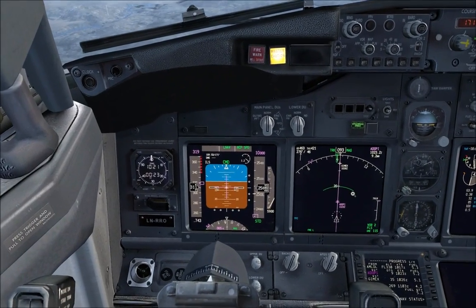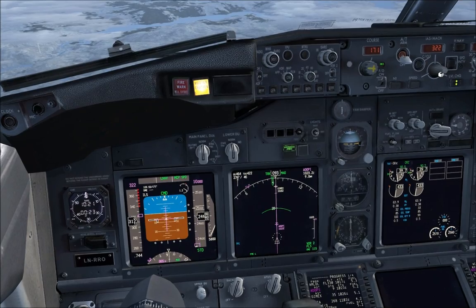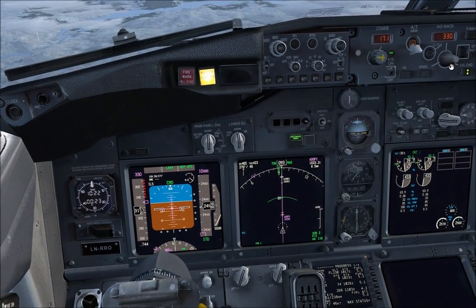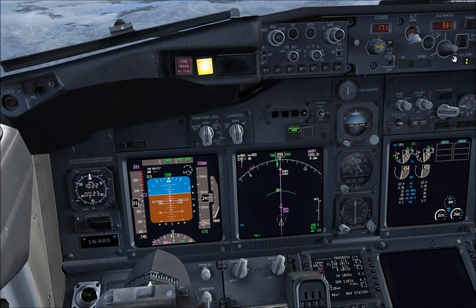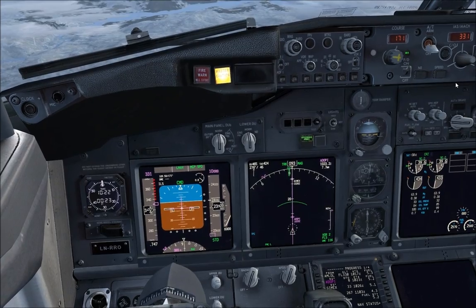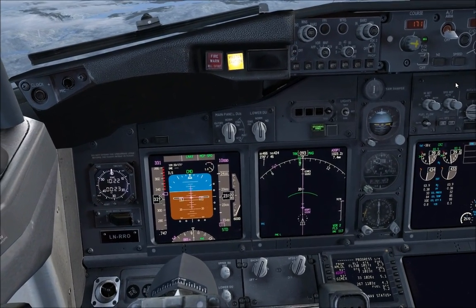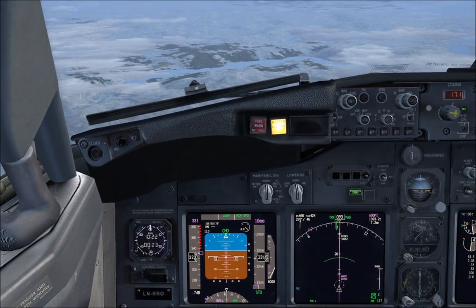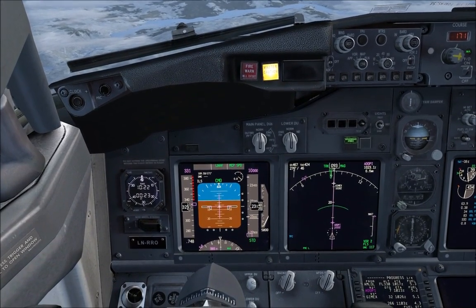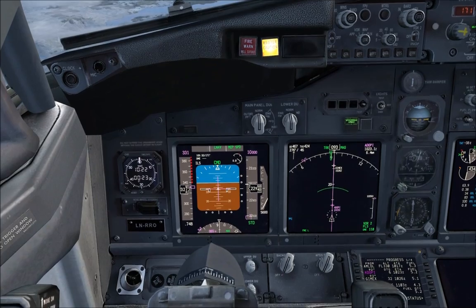To conserve oxygen, move the regulator to normal. Engine start switches, both, as needed. The new course of action is based on weather, oxygen, fuel remaining and available airports. Use of long-range cruise may be needed. Emergency descent checklist complete.